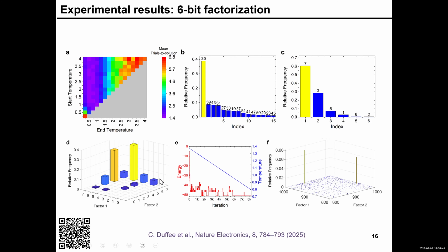You can track the mathematical, really, the energy of this system, defined by that Ising Hamiltonian that I showed you several slides back, as a function of time. And you can see that indeed it is searching through the solution space, and at some point it basically reaches its minimum. The size of the problems that we can address basically depends on the number of p bits that we implement. So it's a function of transistor count and also a function of the bit rate with which we generate these random bits.